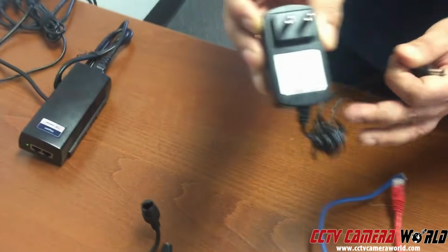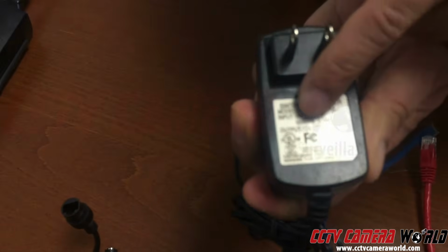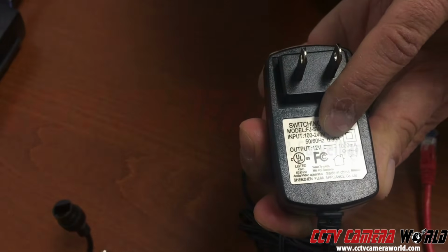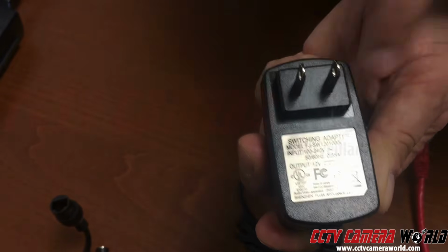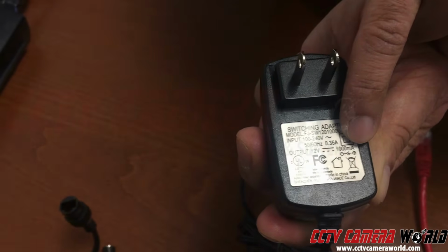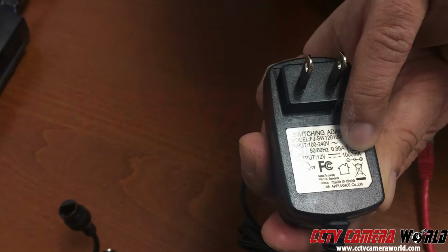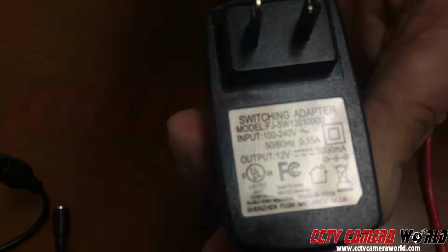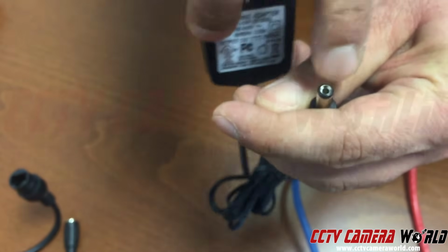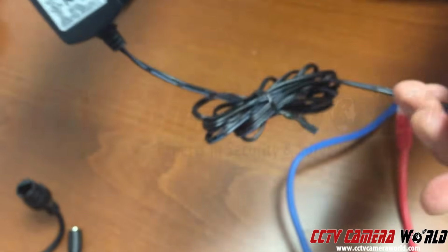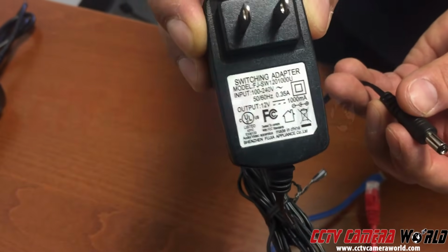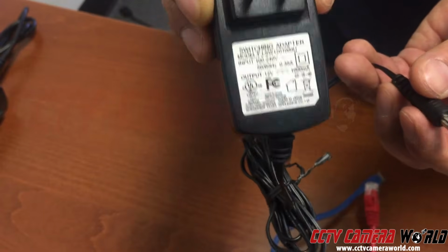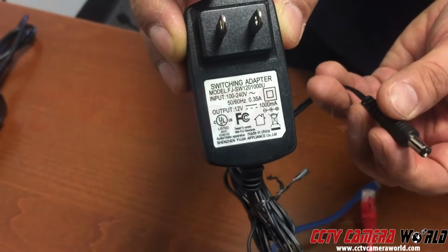This is a 12-volt DC power supply, and it shows here that the current is 12 volts, and this solid line on the top and dotted on the bottom tells me that's DC power. Plus, it tells me what the polarity is. The positive inside the circle means it's center positive. So what that means is the DC jack, or the DC plug, the inside of it is positive and the outside is negative. So this is a center positive DC power supply that's 12 volts and 1 amp. You need to make sure you have a power supply such as this, or you've purchased one from us, to ensure that you don't fry your camera.